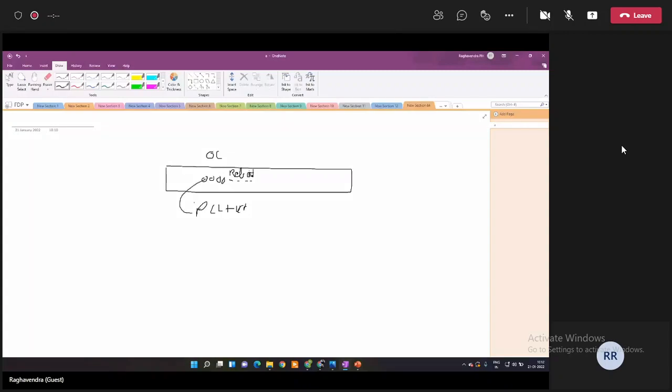So let's say I have USRP1 and it has a local oscillator over here. The reference is connected from one of the ref out wires. There are 8. We can connect one to this. The second USRP, again, the local oscillator's wire can be connected over here.